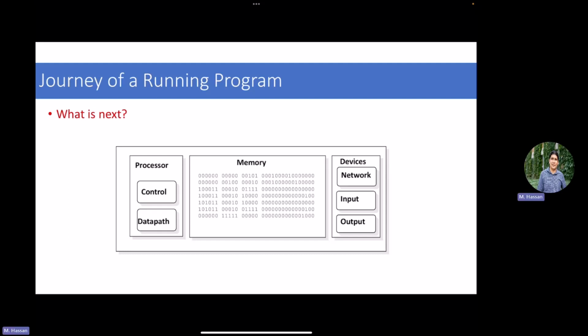Yeah, increment the, oh, good. So it's a good idea. So we are on the right path. So we're incrementing the program counter, but the question is by how much should we increment it? Yeah, by 1 word. By 1 word, yeah, this is 4 bytes, right? Who tells me that the instruction is 1 word? Because now you made an assumption that your instruction is 1 word, right? So this discussion is going exactly where I wanted to go. Basically, this whole thing is making an assumption that your instruction has a fixed width, right?